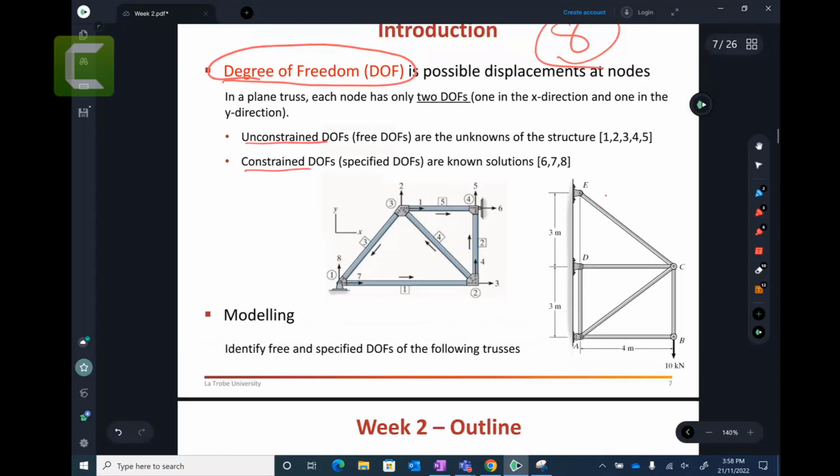Now the story is that these arrows represent numbers, so these are the degrees of freedom. As I mentioned, there are a total of 8 degrees of freedom, so therefore you have a total of 8 numbers there. Now, this numbering is important. All the others before are not logical. You can put arbitrarily whatever you like. But these ones, you need to put with logic. So you need to start with the free degrees of freedom.